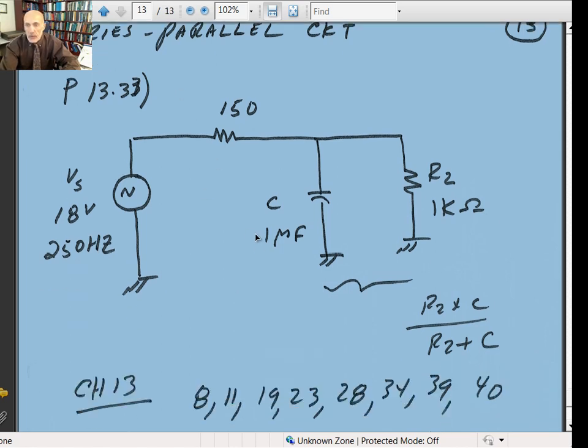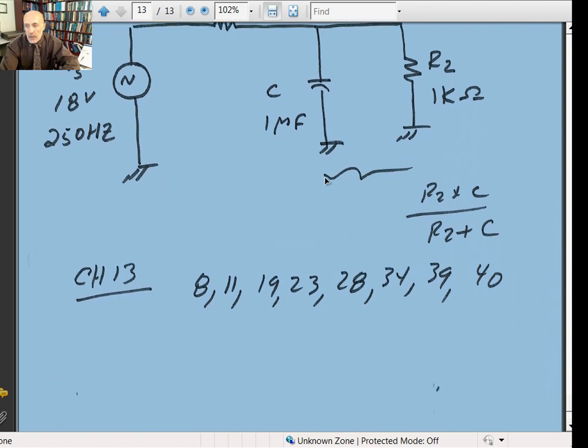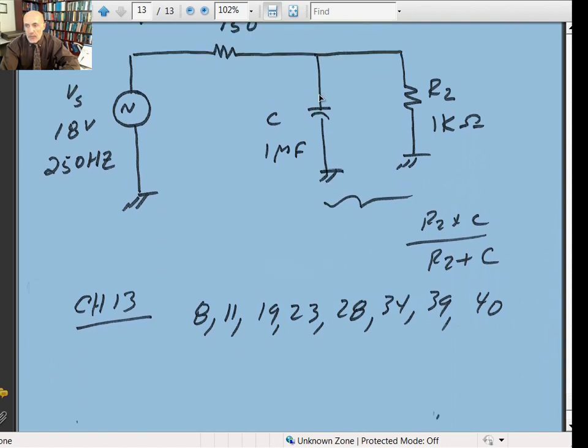But we have to put it in the frequency domain. Once you put it in the frequency domain, then this will be product over the sum in phasors; you can convert it into impedances. And then you add it to 150. That gives you the total impedance, and then you take the voltage divided by the total impedance to give the current. Once the current comes in here, then you can do the current divider rule to determine the current to each load.